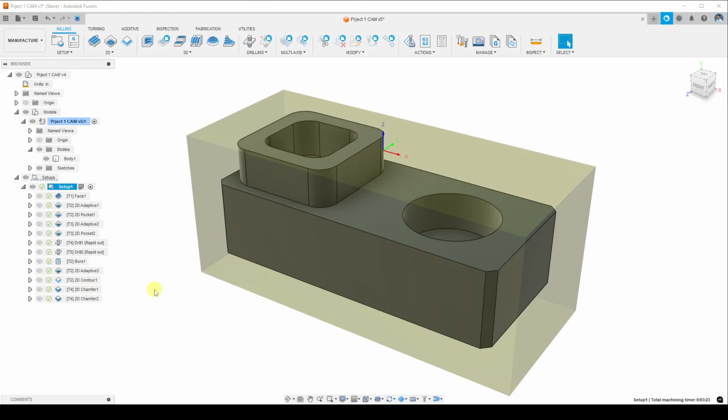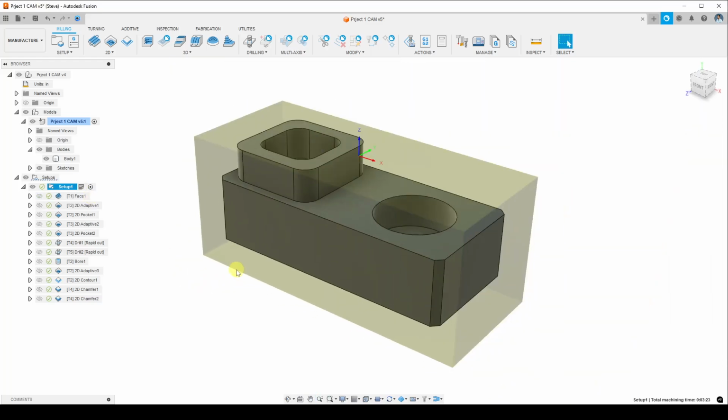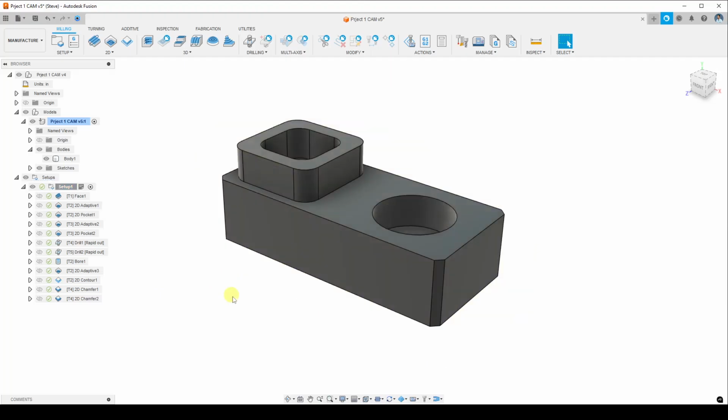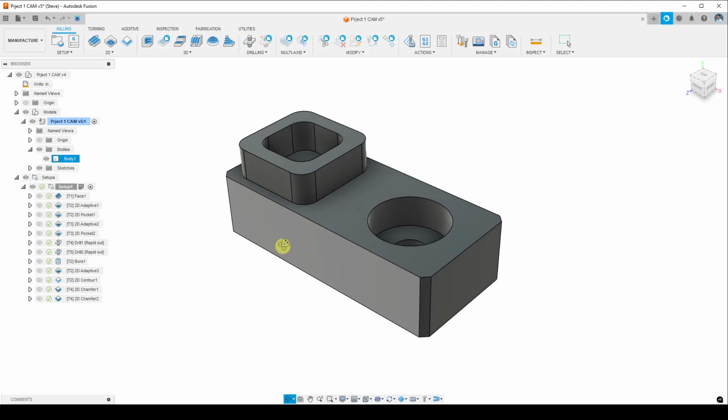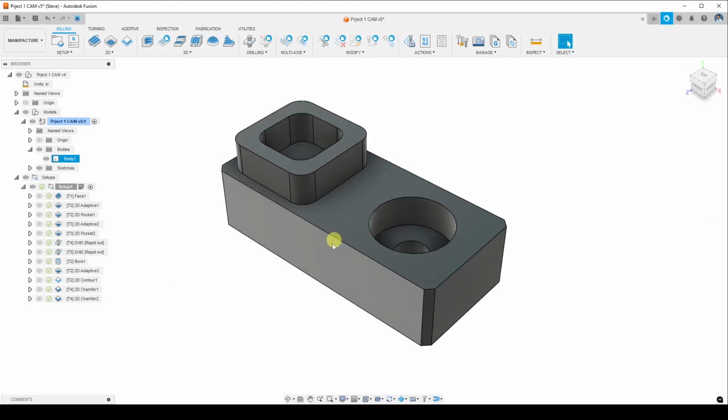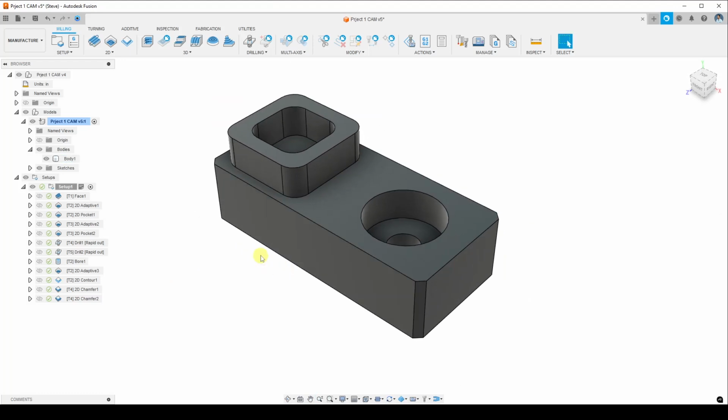Okay, so it looks like we have our machining notes, and the next thing to do, I think, is to make our setup sheet. Our setup sheet is where a lot of really good information about our part or about our program lives in one place. Basically a PDF that has all the information in it. Really important for setting up a machine, and then for running the program, you can go back and see what's supposed to be happening. It's a good reminder of all the details.